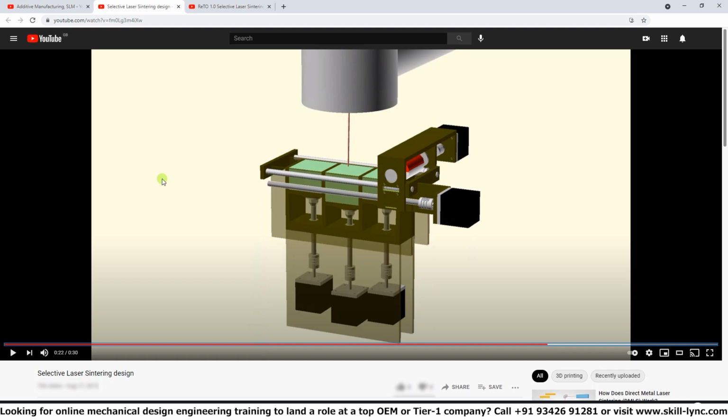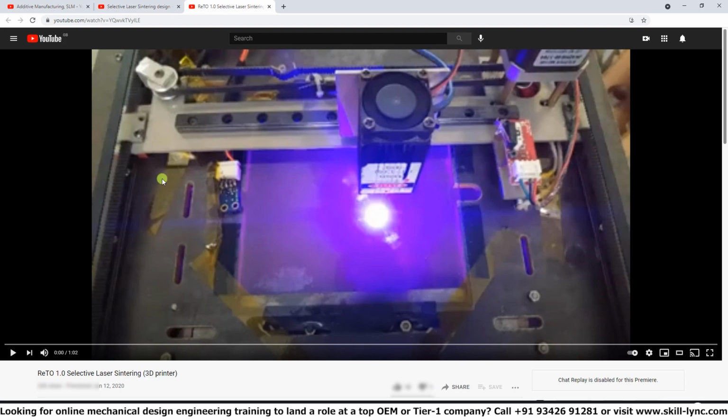So, as we have discussed, selective laser sintering is more used for prototyping processes. Selective laser melting is used more for end parts, so parts that you want to put into direct application. Not just a prototype part that you want to test to see if it fits, and then later on you create a finished part. Using the selective laser melting process, you would directly create the finished part. So those are the main differences, but process-wise, they follow the same steps or the same operation.